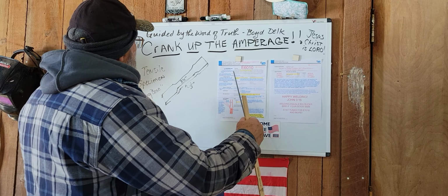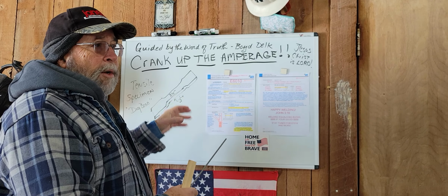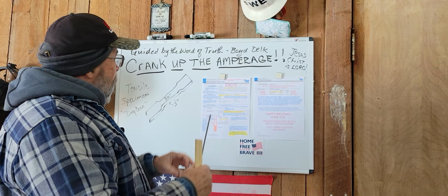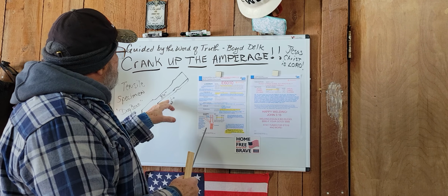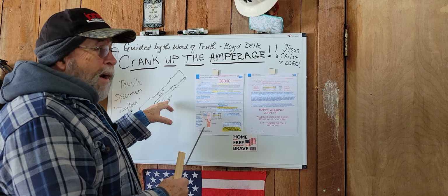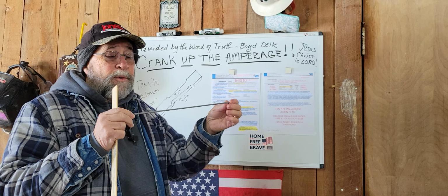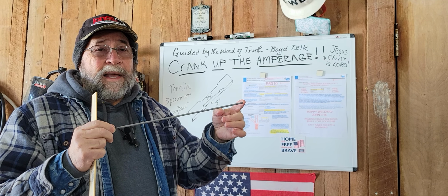So as they're pulling this dog bone apart, it will begin to elongate or deform because of the stress created on it. That's measured as well in the test. But when this dog bone or this base metal fractures, that's the strength of this weld metal. So this rod has a tensile strength of 60,000 PSI.